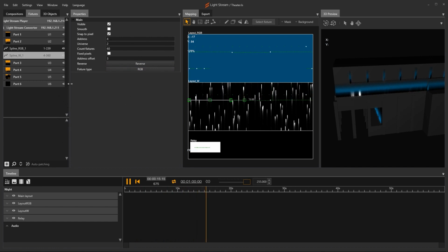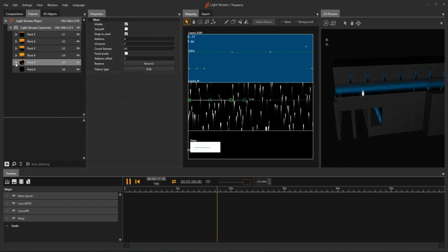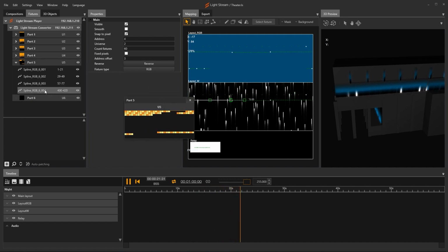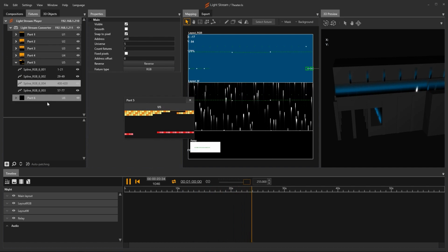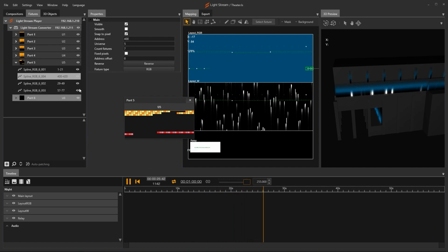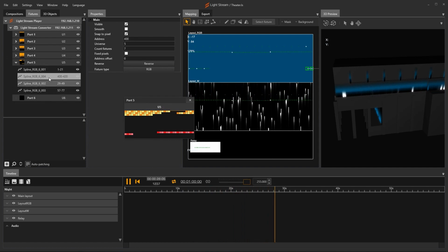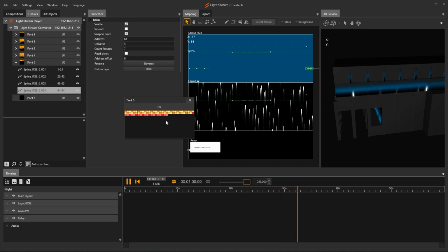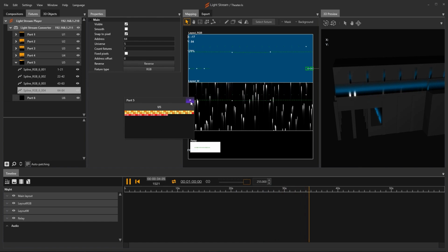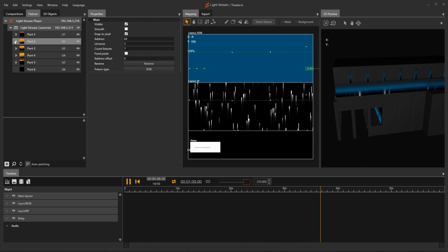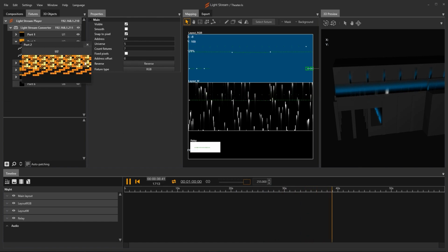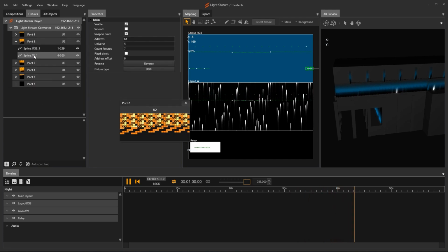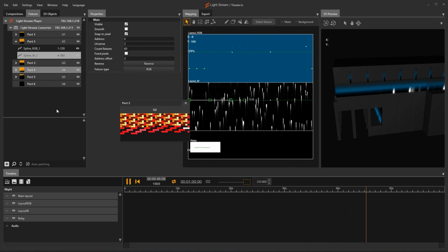Disable auto-patching. By the way, I will also tell you what it is. Auto-patching is required for addresses of other devices to be automatically recalculated when device type or address is changed. With auto-patching enabled, any change in the port leads to automatic recalculation of device addressing. Since devices in the prior project already had the needed addresses, no recalculation is required. Disable auto-patching. We select the devices we need.